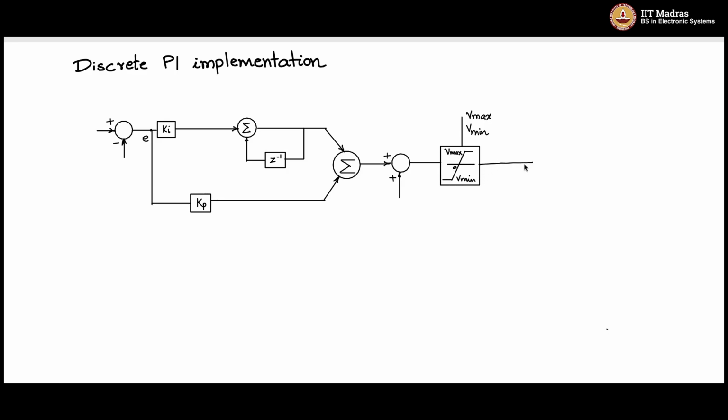So the output of this limiter can be the compare signal for the PWM triangle or the timer. Use this to compare with the PWM timer. So this could be the duty cycle signal, which can compare with the triangle and provide a pulse width modulated signal.